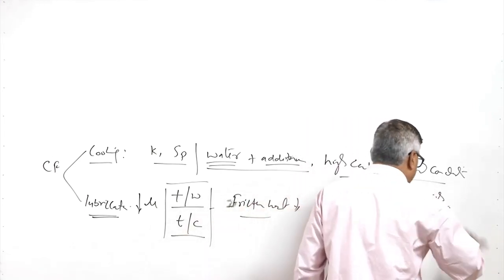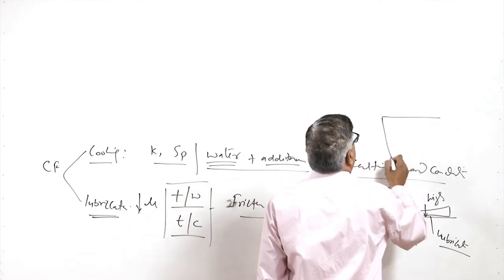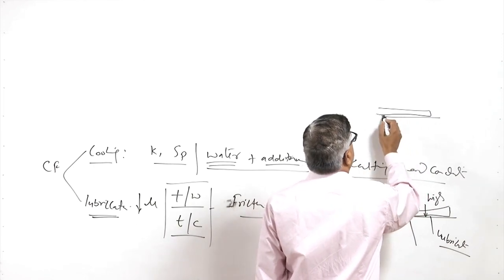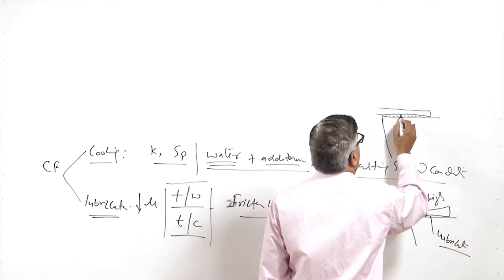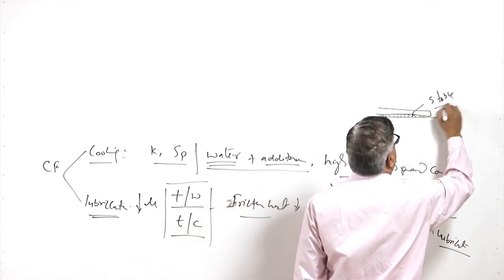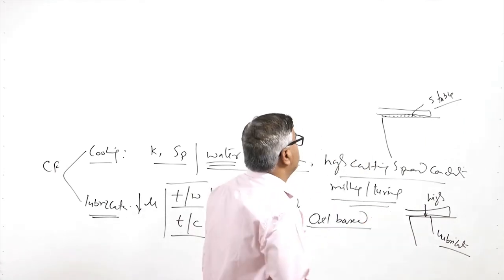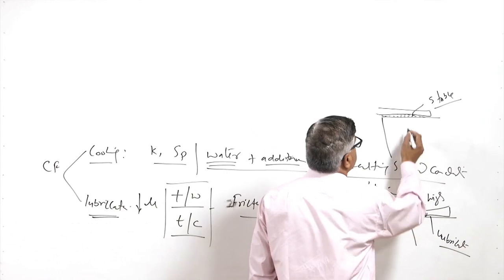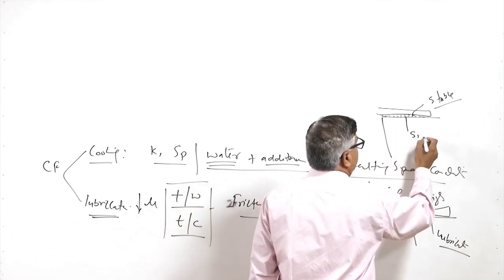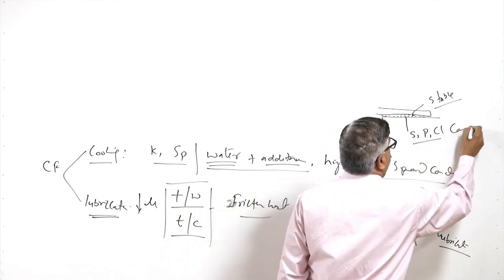So, in order to perform the role of lubrication effectively, the lubricant must be in a position to separate the chip and the tool, and for that it is necessary that the lubricant is stable and does not disintegrate under the cutting conditions of pressure as well as temperature. For this purpose, the oil based lubricants are added with sulfur, phosphorus and chlorine based compounds.